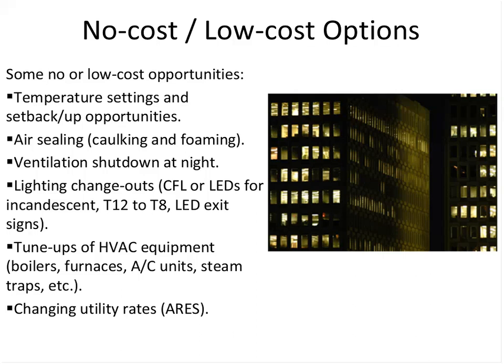Think about tune-ups of the HVAC equipment, boiler tune-ups, furnace tune-ups, making sure the AC unit has the proper refrigerant level in it, because underfilling it and overfilling it both reduce its efficiency. It needs to be just right. If the building has steam traps, think about having a steam trap survey of the building. So there's a lot of things in that HVAC system that can be looked at.